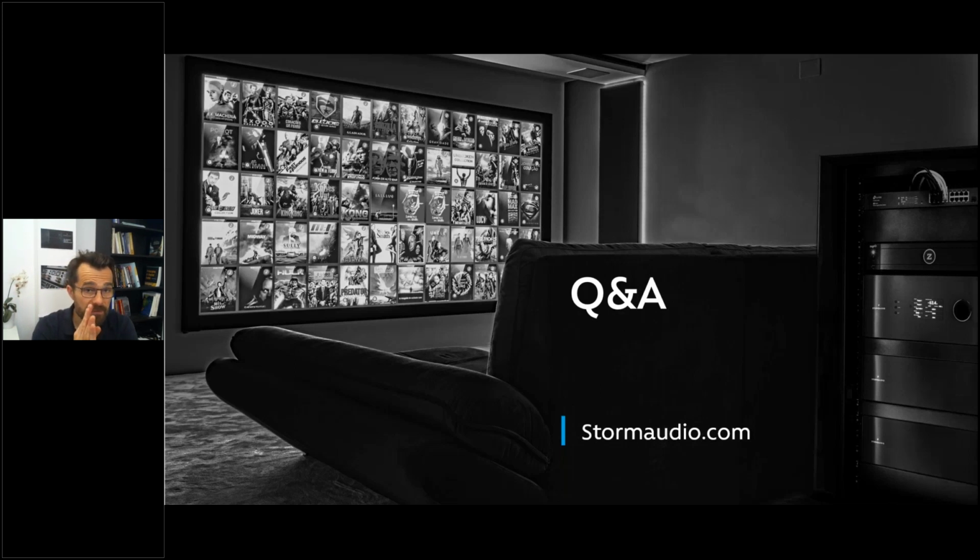So what is critical is to make sure that your main subwoofer in the support group, right, in the main subwoofer groups, is with the infrabass support. The others, you can leave them alone and just support from 20 Hz or as low as they can do, and up to like 150 Hz. So that's what you would do. Okay, so this is done.